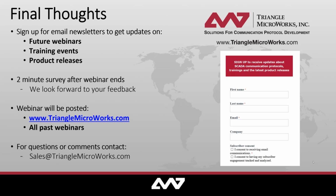To answer the question the other way, why would I want to use client server communications as opposed to GOOSE or sample values? It's the SCADA communication protocol. So it is routable. It can traverse a router. It can go through a multi-tiered network. It uses TCP/IP. There's a lot of great things about it. If one piece of data changes in my data set, I'm only going to notify my higher level system that, hey, just this single piece changed, and my report therefore will be a little lighter weight on the wire. I hope that answers the question.